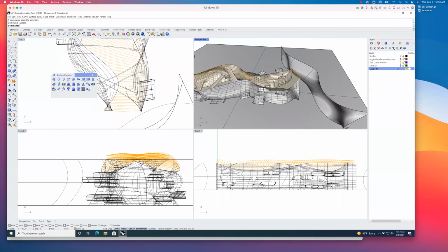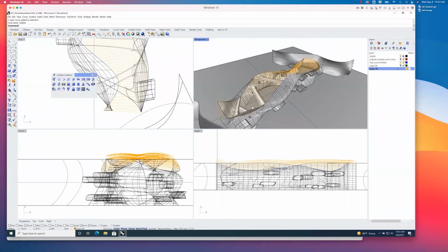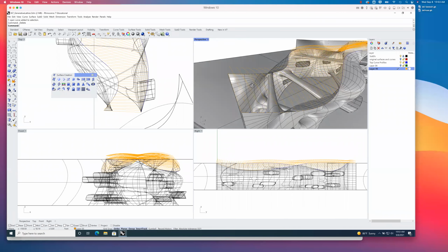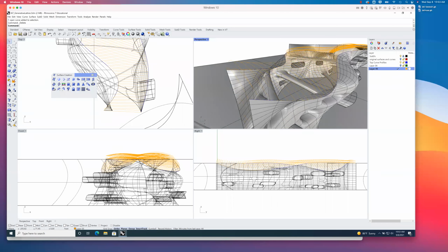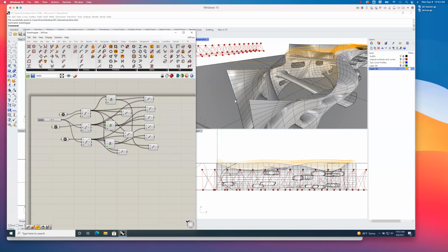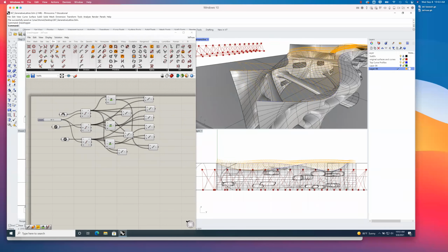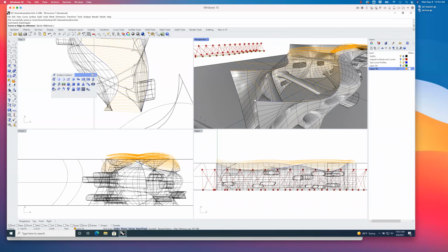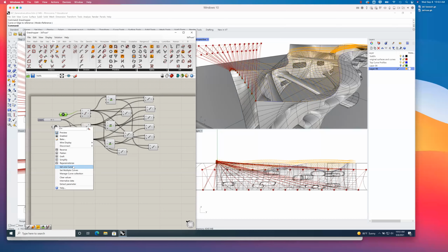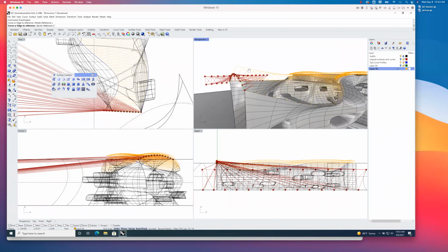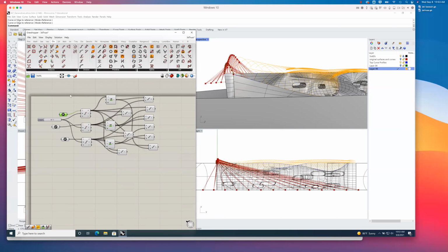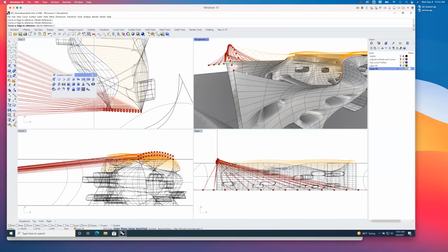All right. And now, last but certainly not least, it's time. I'll just go ahead and save this really quickly. Go ahead and open up Grasshopper. And let's make one of these three-dimensional trusses. Okay, in this case, I'm just going to pick these curves and say set one curve, and I'll pick this one. And I'll set one curve, and I'll pick this one. And then set this last curve, and I'll pick this one.